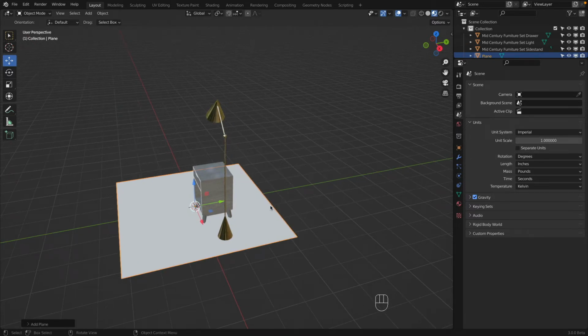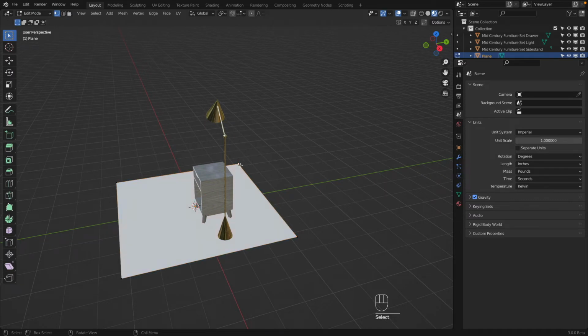This line here, I would like to draw up a little bit. We will also learn in this video a little bit how, for example, polygon modeling works. And you will see that it's pretty much the same as in SketchUp. Slightly different, but the same. We switch into edit mode. In SketchUp, you double click an object. Here we switch between object and edit mode. Then we can click this, shift click this, and then we can extrude this one up.